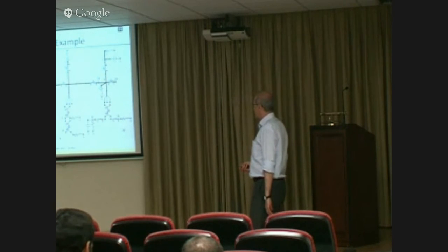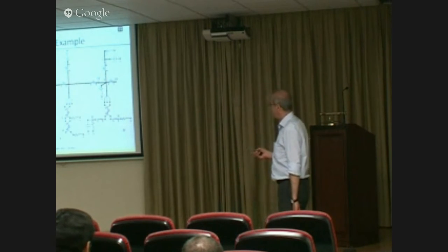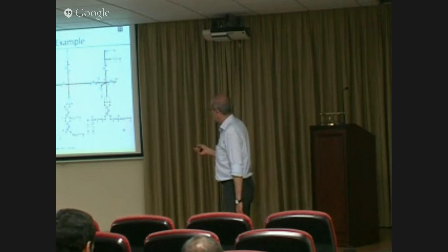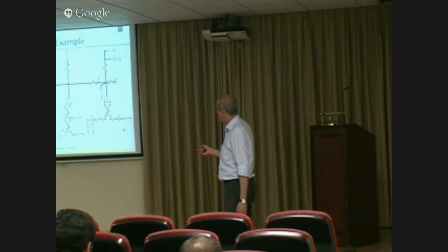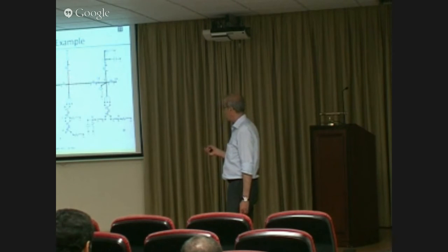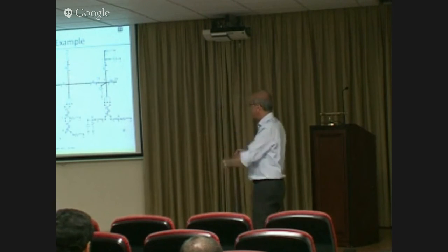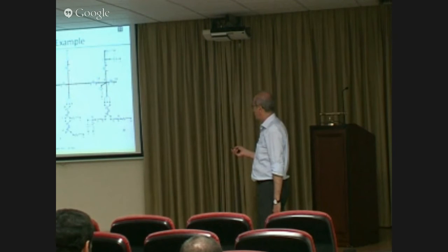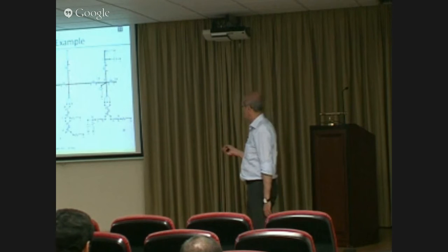And what we did is we applied a fault along this branch 2 to 5, which is a three-phase branch, and applied a double phase to ground, double line to ground fault along this branch about a third of the distance of the entire branch from the line terminal end 2.